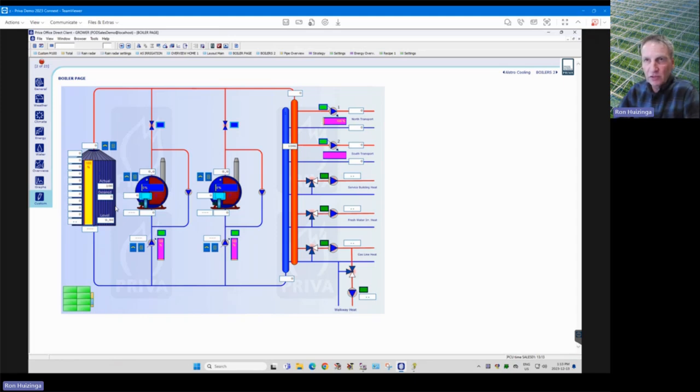There are systems with a nitrogen layer on top of the tank, a pressure tank, which controls the water level and the pressure in the system. And then there's the system with no nitrogen layer on top of the tank, just an open air to the outside, and in those tanks we put a level pressure sensor, so you see how much water is in the tank.